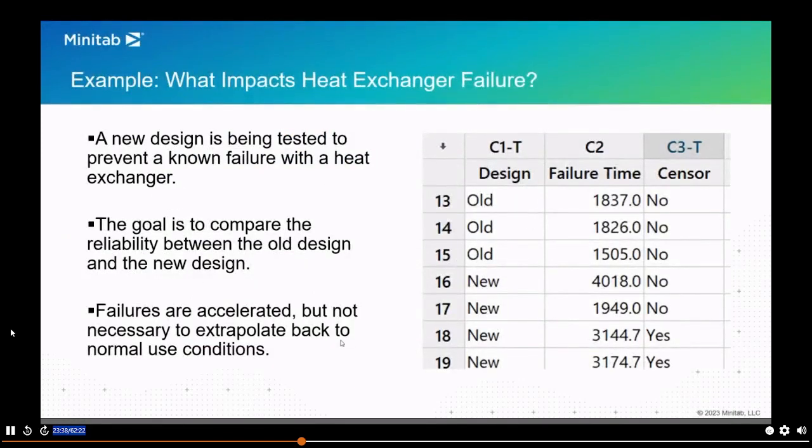All right, so we've done the warranty prediction with the data that's out there. And what's really cool is, again, we don't have a lot of failures, but we're using all of the systems out there to actually get these predictions, right? We're taking all of these units that are out in the field, still running, not having failed, to get really accurate predictions of how many might fail. So we've used censoring to be able to get these really good data points of things that we have kind of no data for, right?